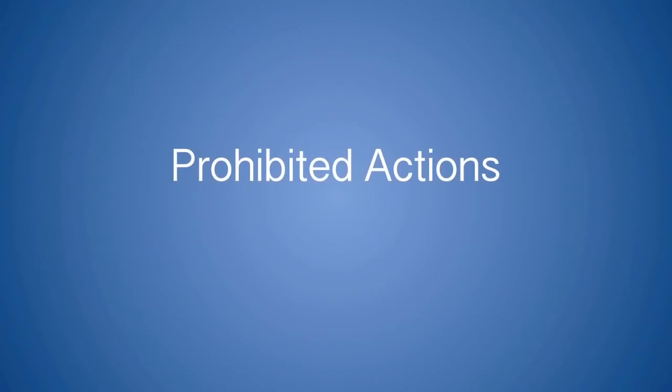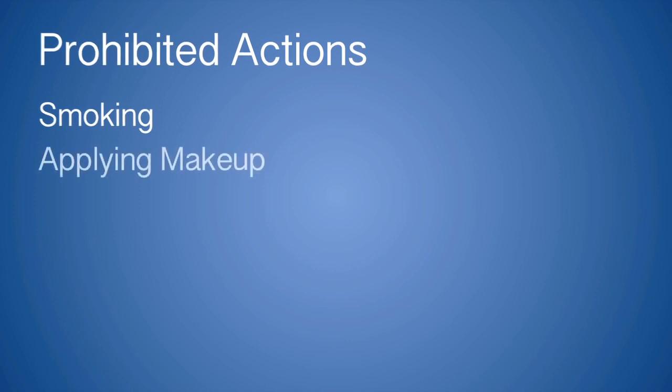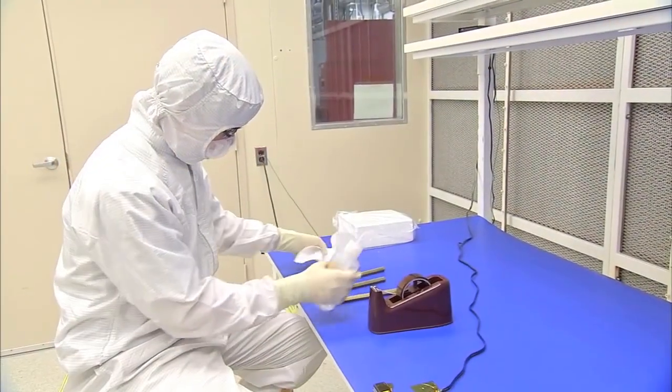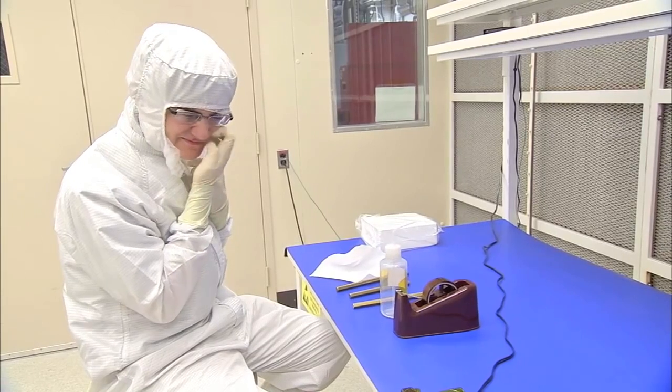Prohibited actions. While in the cleanroom, a number of behaviors are prohibited as they introduce unnecessary contamination. Smoking is absolutely prohibited in the cleanrooms as it introduces a vast number of unnecessary particles into a cleanroom. Applying makeup in the cleanroom is also prohibited, as makeup is a huge source of contamination. Touching one's face with gloved hands introduces skin and oil to gloves, which then gets transferred to hardware and other